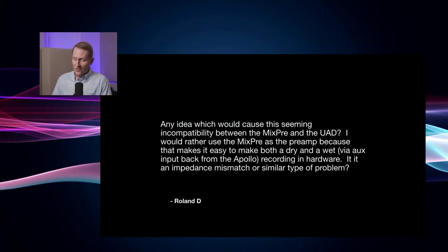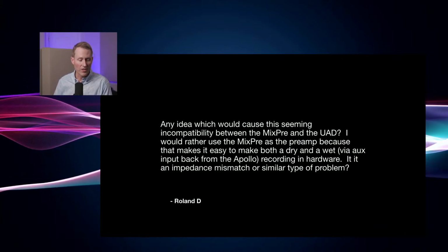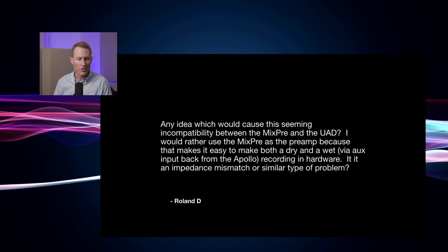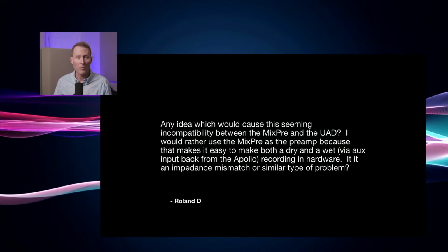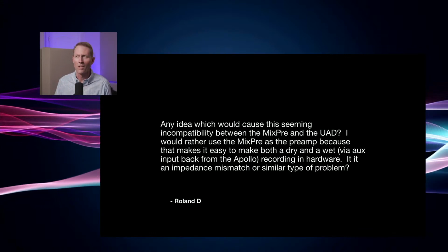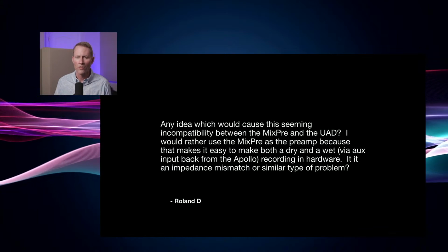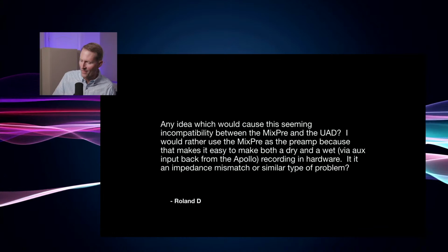It is actually just a problem of sending unbalanced audio, stereo output, into a balanced input. So you just need to use a DI, is what it sounds like. So using a DI would solve that problem for you. I'm 90-some percent, I'm going to say 99% sure that that would solve the problem for you. So that's what I would give a try to, Roland.